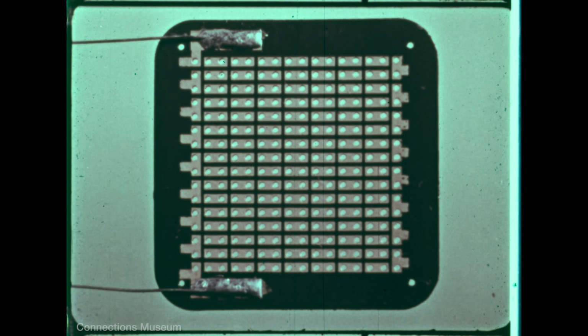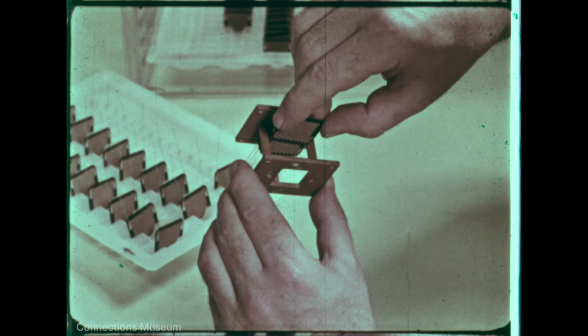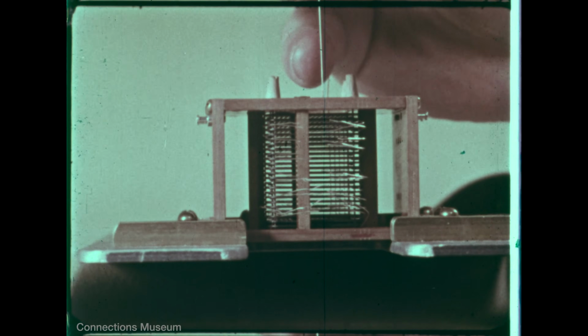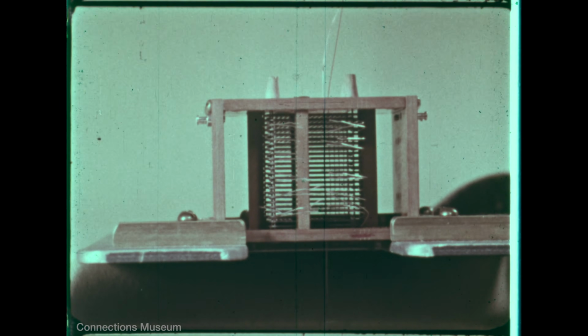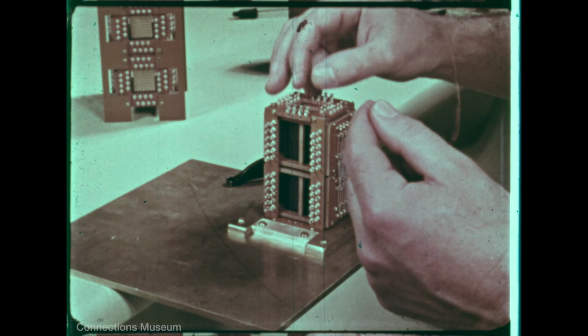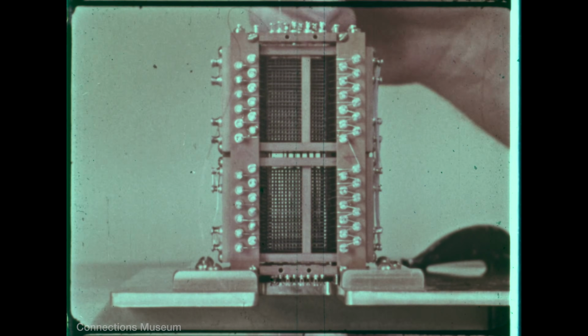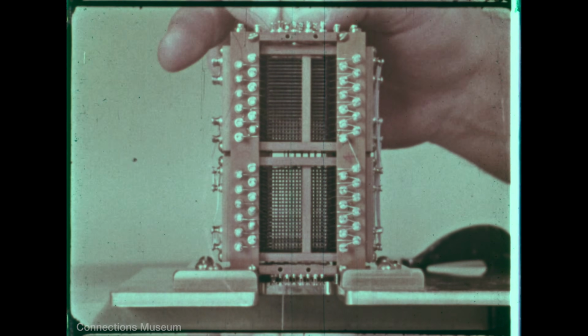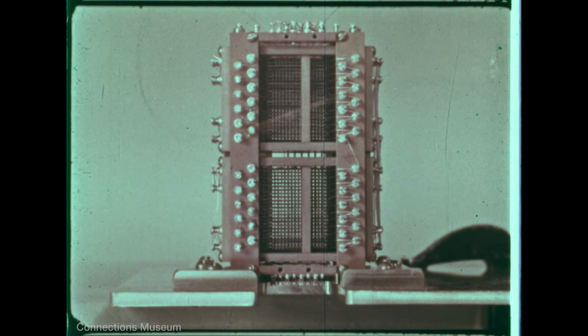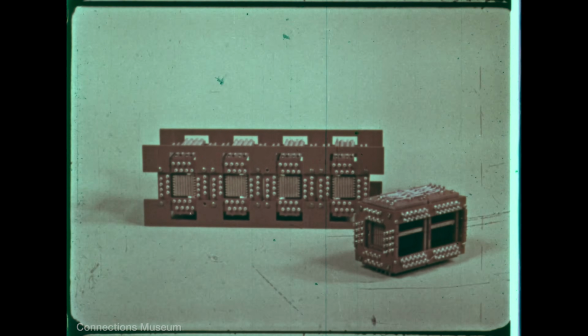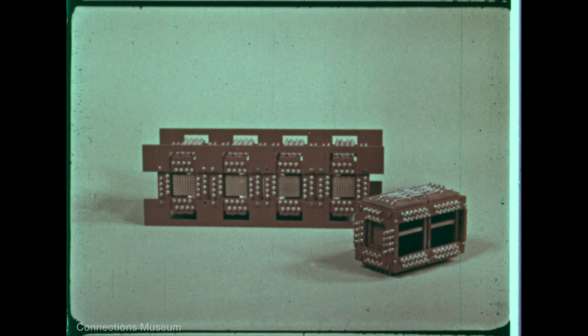To form a memory, 24 sheets are stacked in a frame. Then thin copper wires are threaded through the holes in all sheets, forming 16 parallel planes of inhibit wires. Then the stack is joined to another stack by threading 16 planes of X wires, making a module of 256 48-bit words. Modules can be interconnected to form larger memories, such as this 50,000-bit one. It takes only 1/4 the space and costs about 1/10 an equivalent core memory.